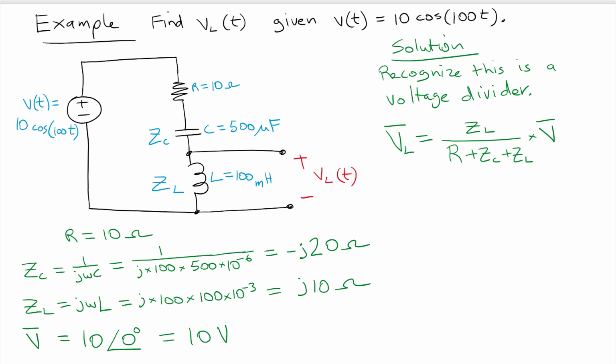And the expression for that is 10 at an angle of 0 degrees. And where do we get that from? Well, 10, that is the amplitude. Okay, it's 10, that drops down, and there's no phase angle here, so there's no theta, right? It's equal to 0, so that's what we've got here. And so it's basically just 10, and its units are volts, so 10 volts. So that's the phasor voltage of the stimulating source.